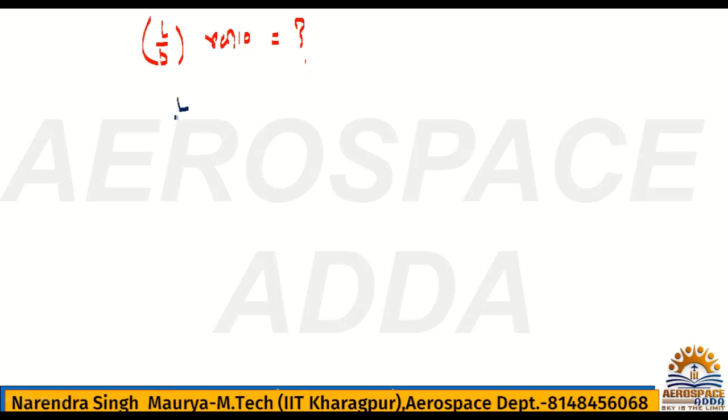L by D, as usual, for steady level flight you can write CL by CD. There should not be any doubt. At the same altitude, L by D will be CL by CD, because density should not change.